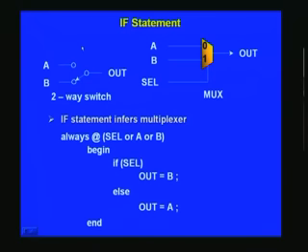And we have also considered the if statement. We revisit that in order to see what exactly the synthesis tool maps. You are all familiar with a two-way switch. You would have used a band switch in a radio, for short wave and medium wave. They are basically SPDT, single pole double throw. It rests in either this position or that position in a mechanical switch. You can simulate this one, and you can get out either signal A or B, depending upon this rocker.